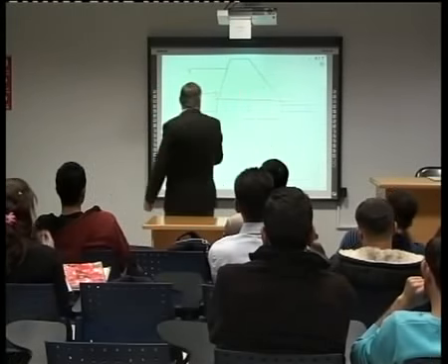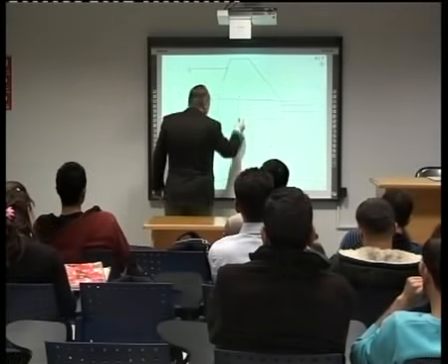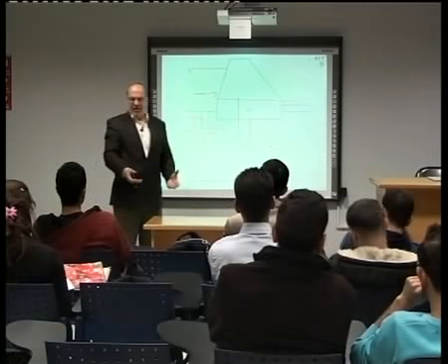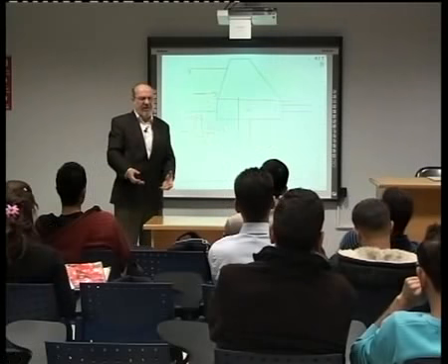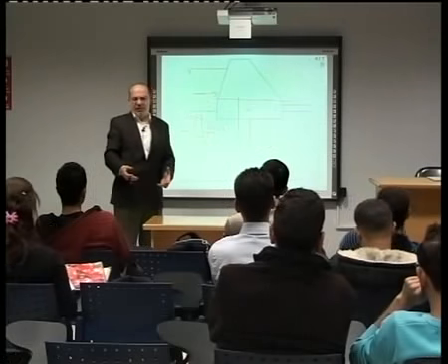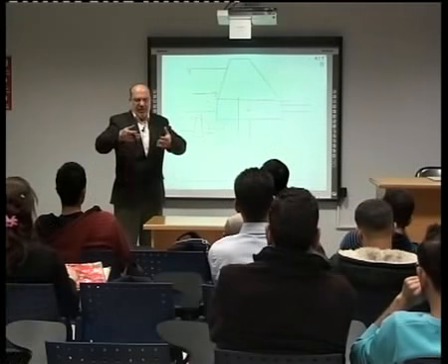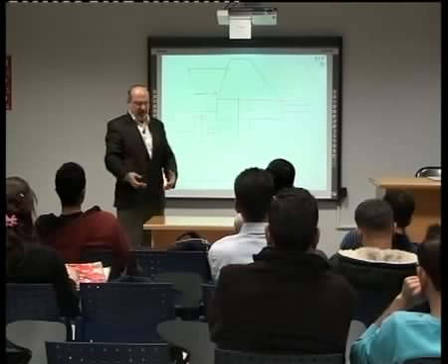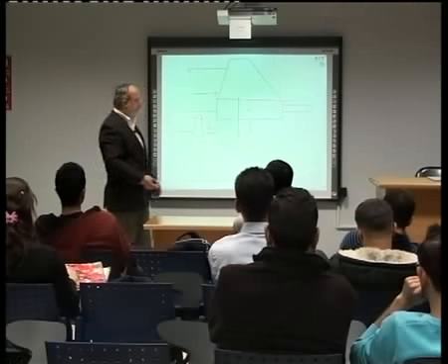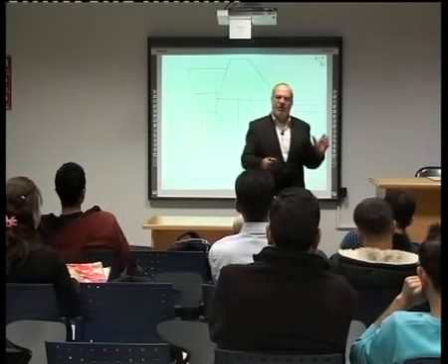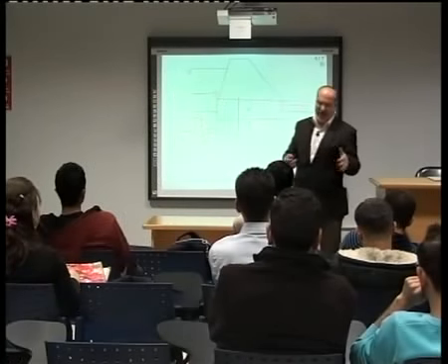And also I may have sinking problem. The dam is very heavy. The rocks or soil beneath it cannot hold this amount of pressure, this heavy weight. So the dam sinks. Okay? Sinking, settlement. Okay? These three problems should be solved through courses of structures, reinforced concrete, etc.